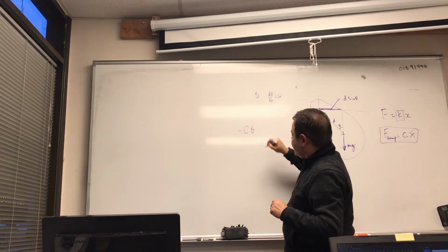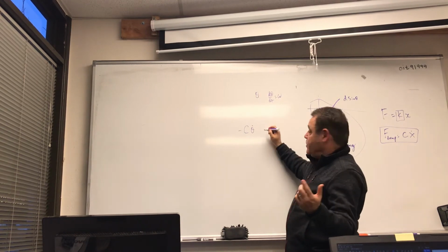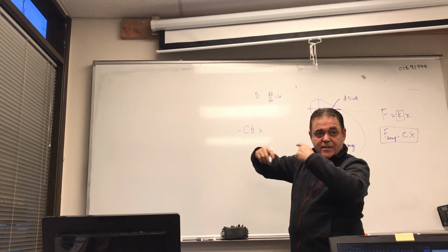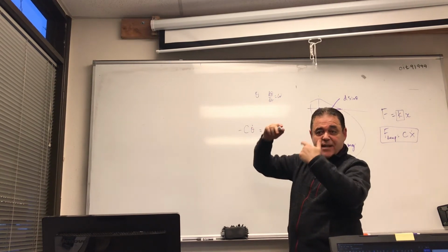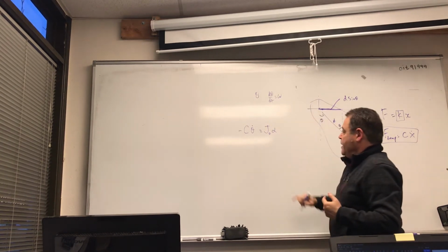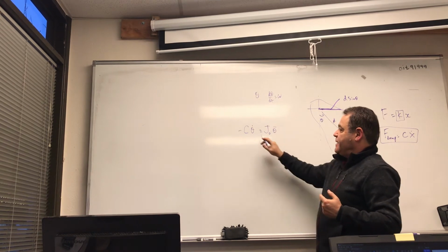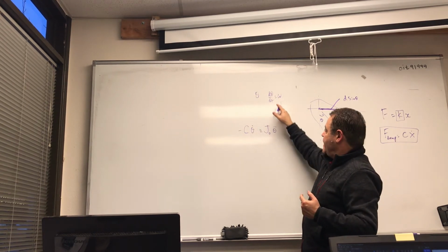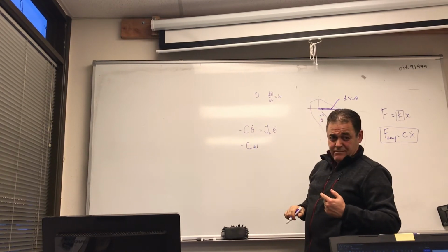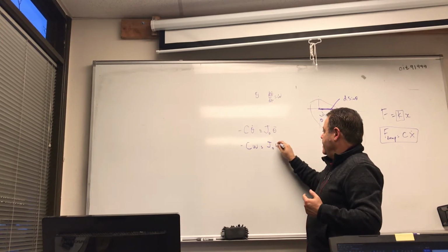Well, let me call it c theta dot for now. That's the only force. The sum of the forces is equal to what? It's rotation, so instead of ma, it's going to be J naught alpha. But alpha we know is theta double dot, and now I can come back here and say this one is omega, and theta double dot is simply omega dot.